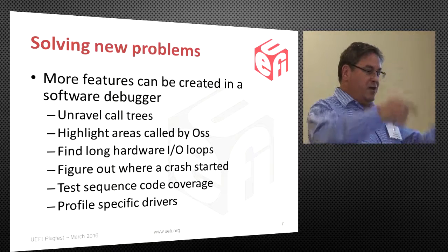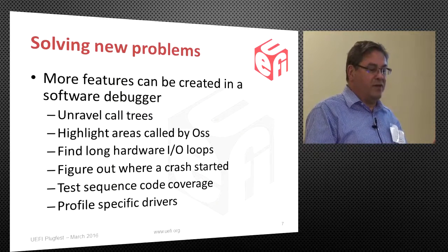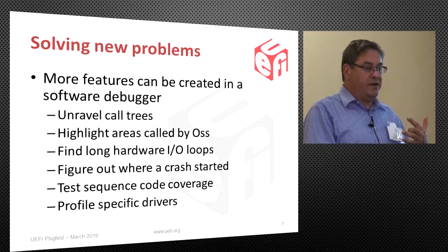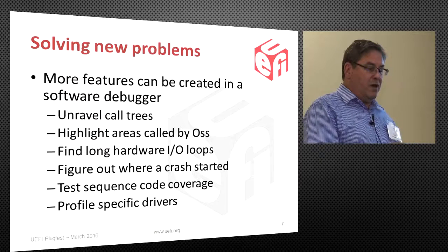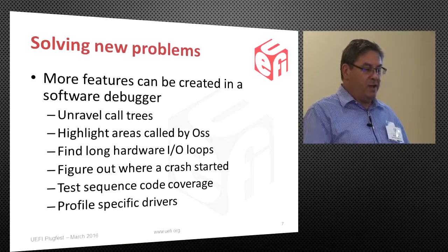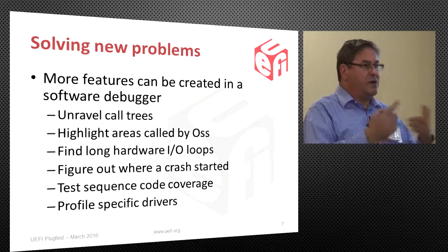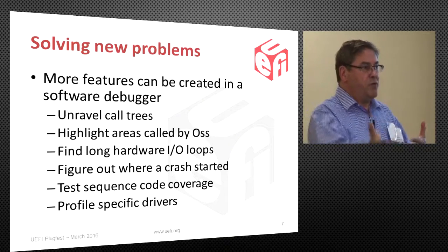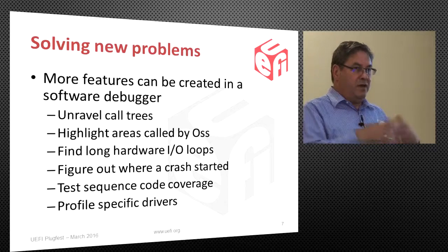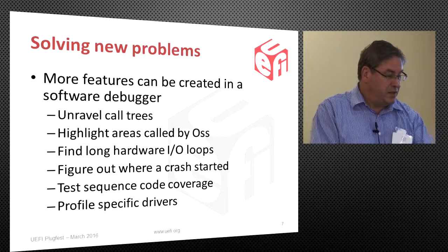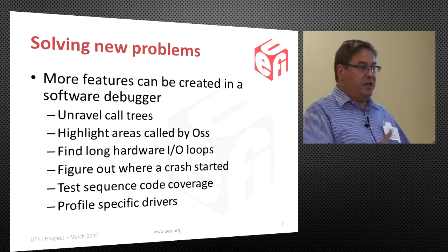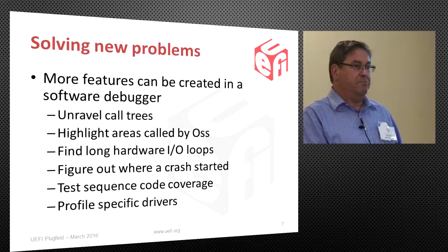We can actually unravel call trees all the way back. We can highlight areas that were called by an OS during POST, or as you're bringing the OS up. We can find long hardware I/O loops and point those out to the programmer, so that if you have a really slow POST process, you can go through, figure that out, and find out where you're spending all your time.